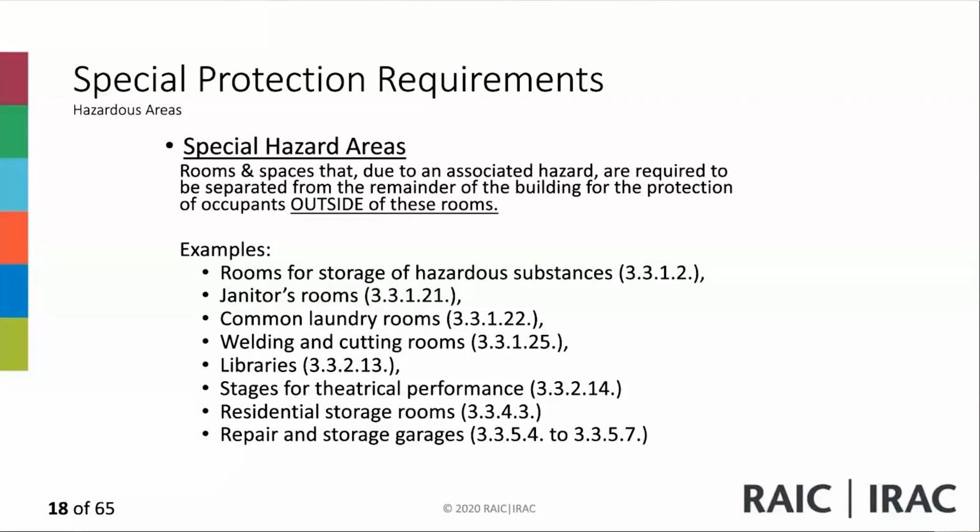So when you're a repair garage and any ancillary spaces serving it, they also include the office spaces, the supervisory office space, the storage areas, the waiting rooms. These are all part of the repair garage. That repair garage, if it's adjacent to a sales office, the sales area needs to be separated by a 2 hour fire separation.